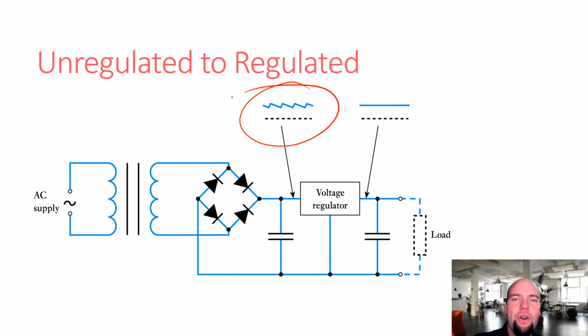If you look at the back of them, they'll usually say something like 120 volts AC to 9 volts unregulated. 9 volts unregulated means it's kind of 9 volts, but it's got this messy ripple, right? It's about 9 volts. It's DC, so current only flows in one direction, and it's somewhat filtered out, but it's not being controlled. We're not actively maintaining an exact voltage on that output.